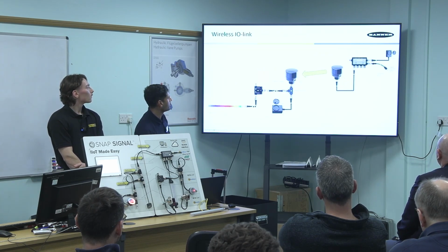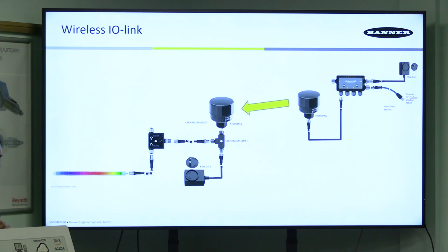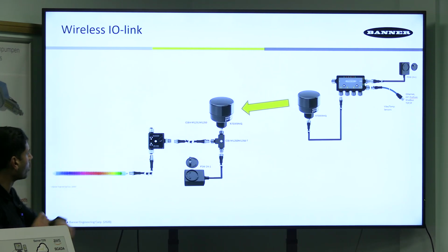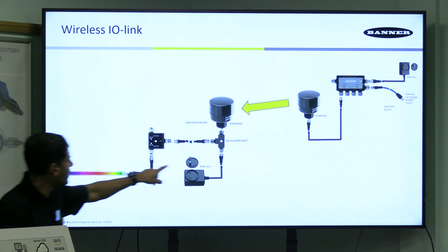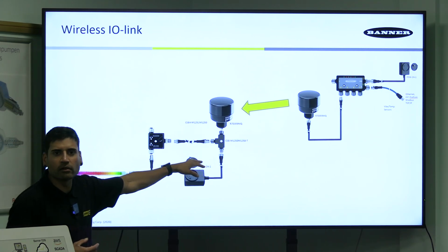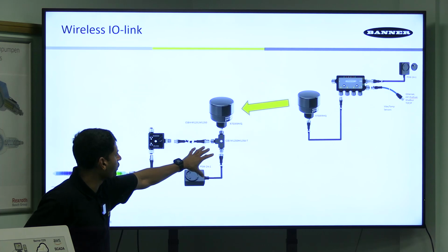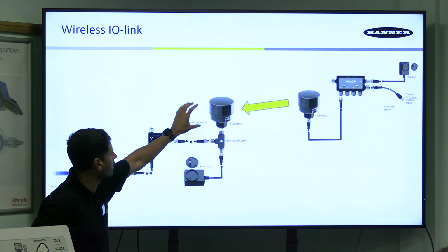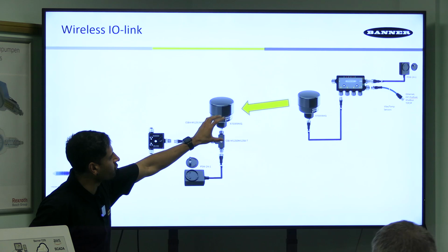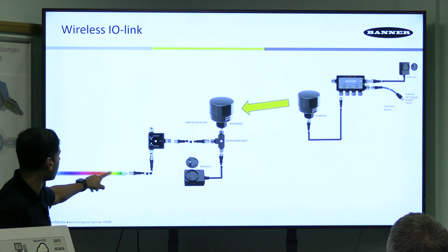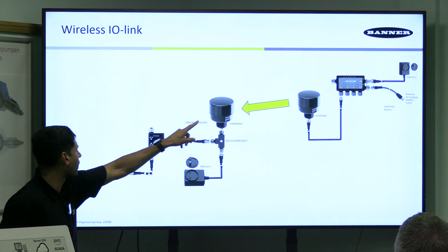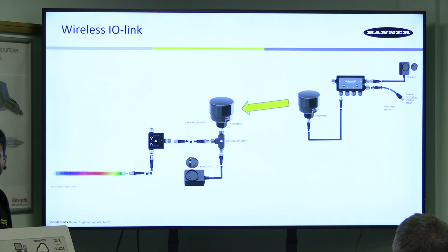There's a few more. And this is a way we can, with the radios that Craig mentioned, wirelessly transmit IO-Link signals as well. So we can use one of our IO-Link 2-port masters. Got power on, like I said, it's parallel. So we power it using the splitter. The client is getting powered, and then the server radio is going back to the controller. So it's sending this signal from here, to here, to control the light wirelessly via IO-Link.